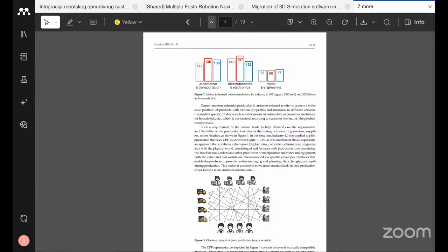For example, in the pressing module, the sensor will check the status of the workpiece. The PLC will stop the conveyor once the box is coming. The sensor will check it and send a message to the PLC.